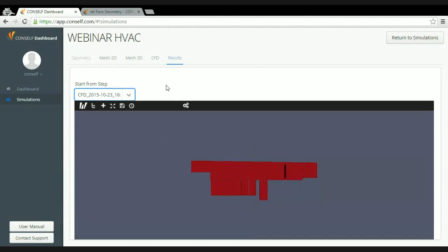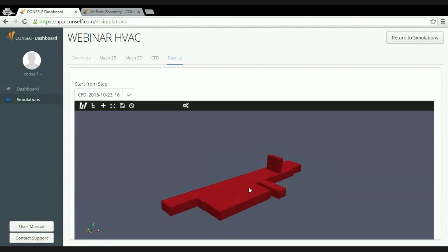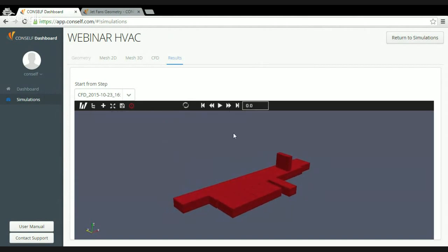It is a little bit like after having performed a wind tunnel test, and we now have a huge amount of data, and with this data we want to analyze and see whether we are happy with the ventilation inside of the car park for this particular case. Well, let's move first of all to the last saved time step.